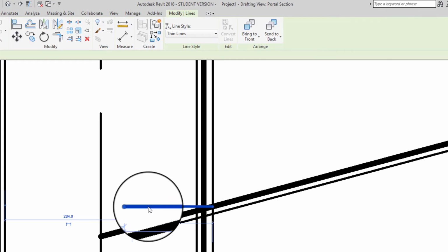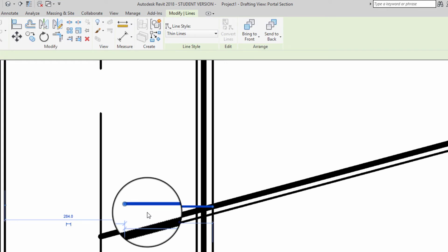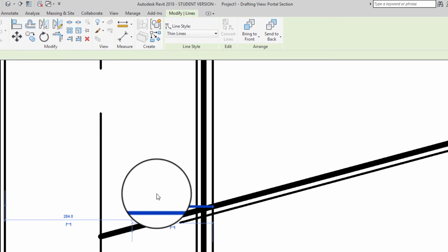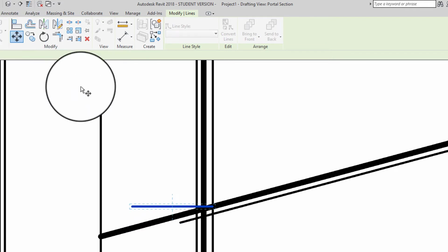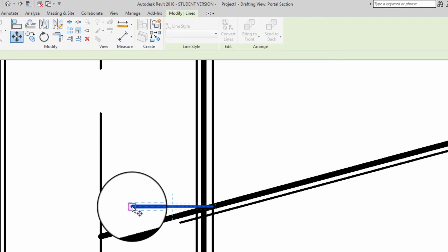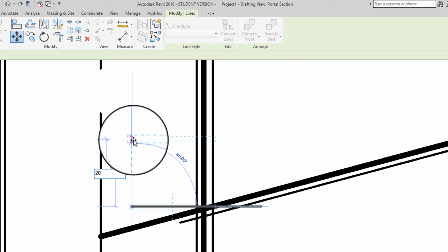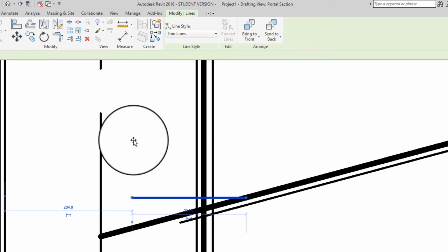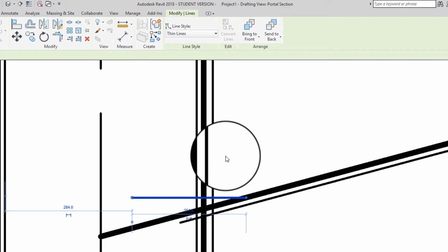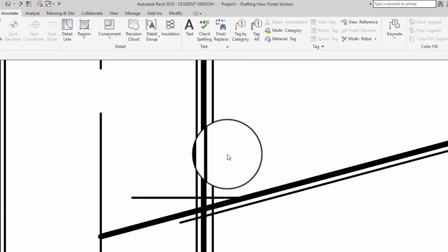And as I said just now, we want to have the top of the end plate 20 millimeters clear of the rafters. So select the line for the top of the end plate, and we're going to move it. So select the move command from the end point, drag it up and type in 20 and press return. So that's going to be the top of our end plate. So escape, escape, and that will cancel that command.